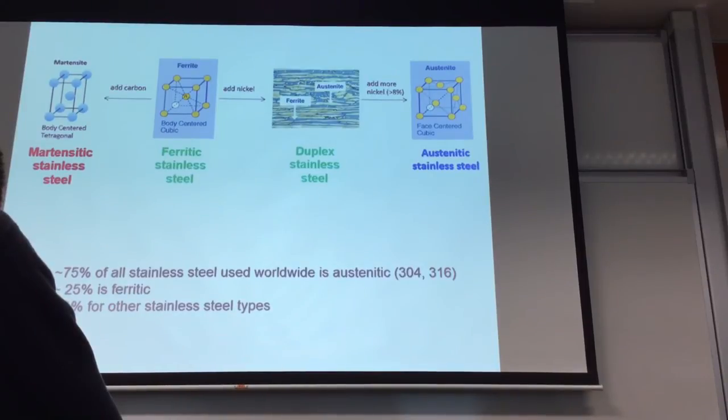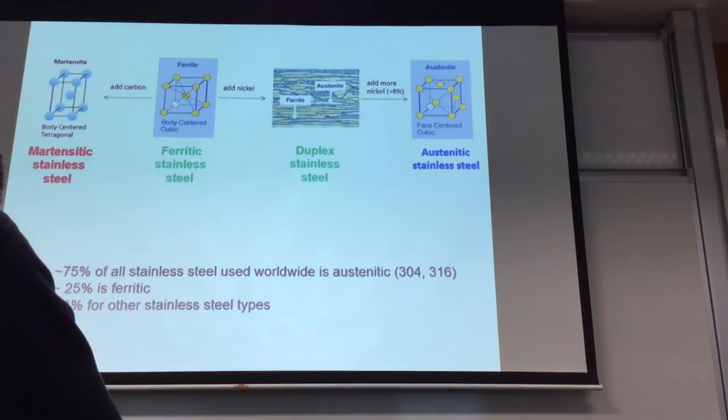What are the elements? The main one is what? Actually, you know about all this already. So, the main element is what? The main element is chromium. Okay, you have about 16 to 20% of chromium in this. So our ferritic stainless steel has a ferrite microstructure. It's basically steel plus a lot of chromium, basically about 16 to 20% of chromium. That's why we can get the stainless steel.